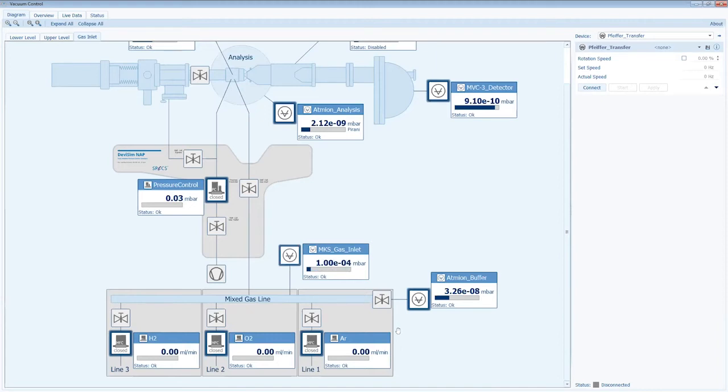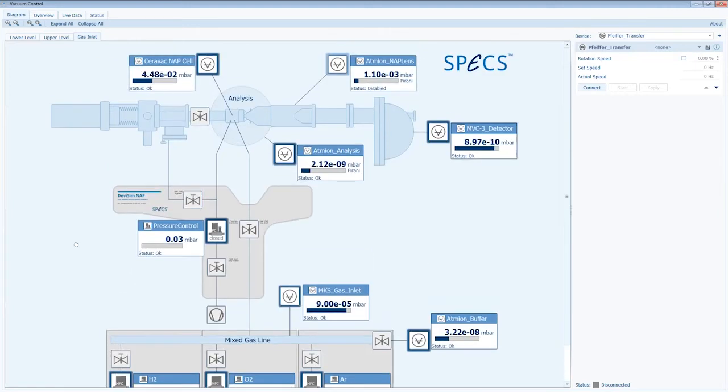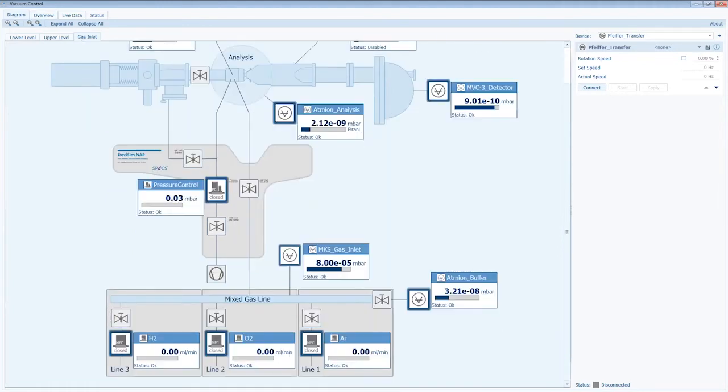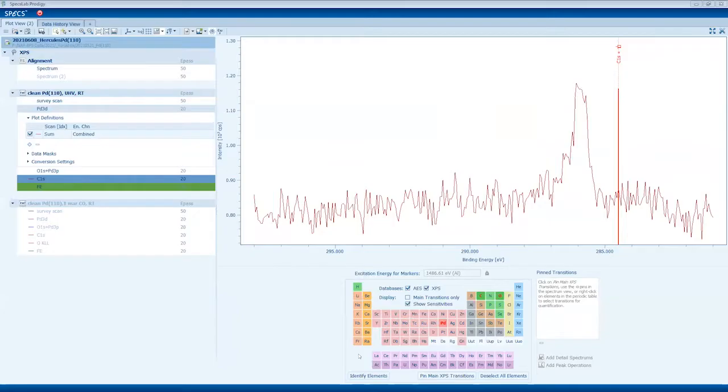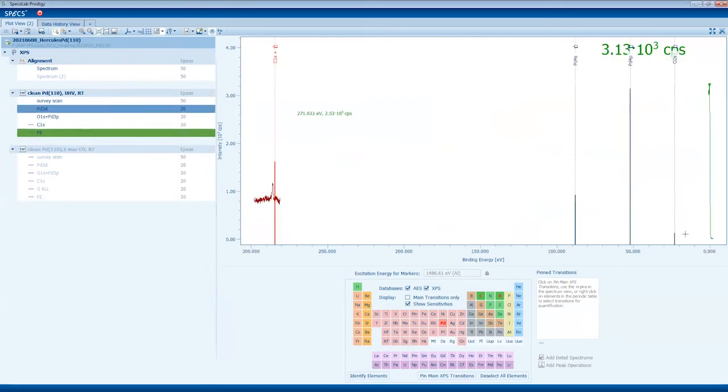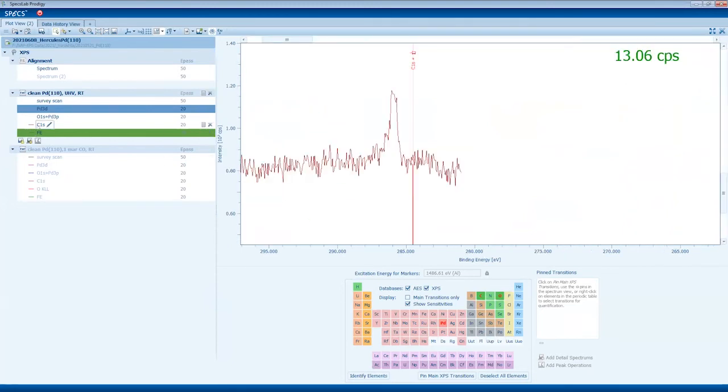So we are adjusting the flow in such a way that we have the required pressure which we want to have. However, of course, sometimes people would like to keep a ratio. So they want to have two moles of one gas and 1 mole of another gas, so they try to set the flow in such a way that they keep this stoichiometry. In this case, we can do it in 2 ways: we can recalculate the flow using some tables which we have here,